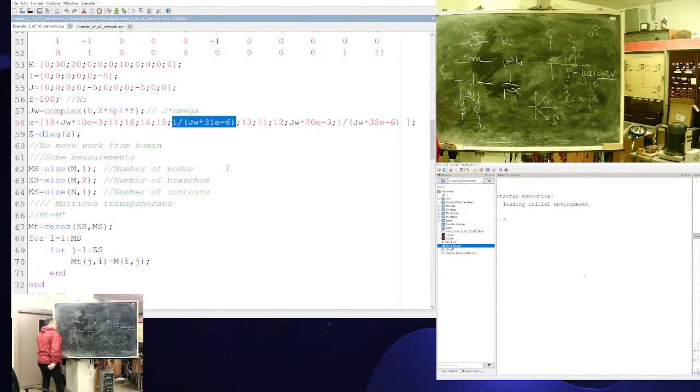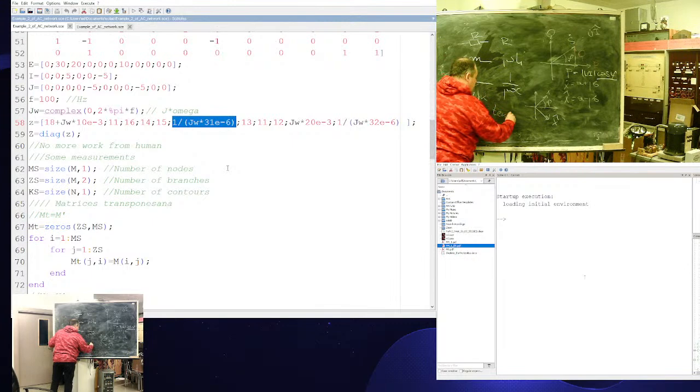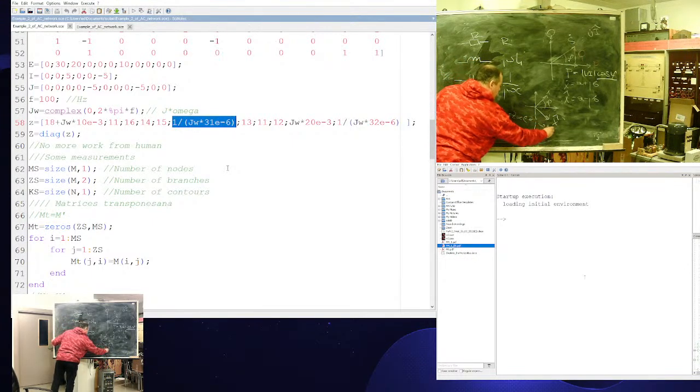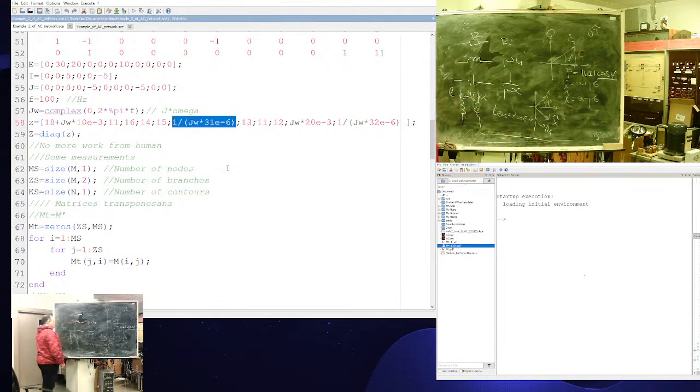But at the moment you have coupled branches. Let's say this is A and this is K. That AK will be equivalent to KA and equivalent to j omega M. Until you have mutual inductance, your resistance matrix will be pure diagonal.